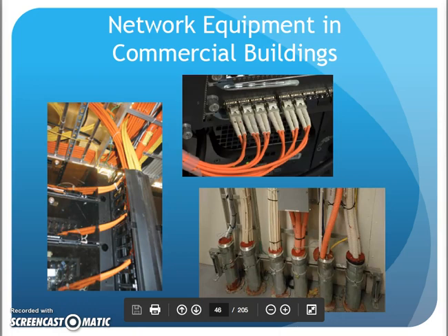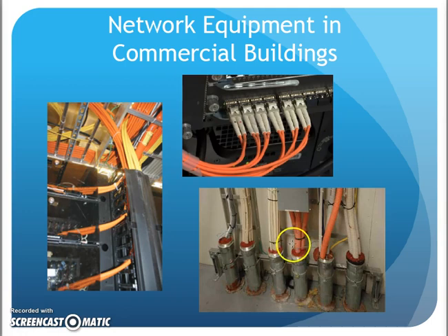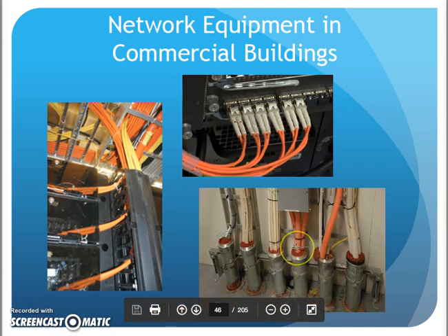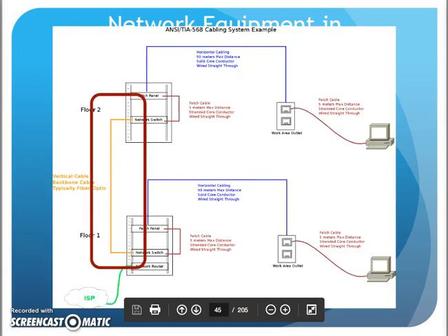And here is actually some examples of some backbone cabling, some fiber cabling going between closets. And literally in a multi-floor building, there is a hole drilled through the floor, a metal sleeve put through, the cables go through. Here's actually fiber innerduct. It's a plastic hose, almost reminds you of a swimming pool hose, that the fiber cables go down through. That hose is there for protection and a guide. And then after all this goes down through this conduit, this sleeve between the floors, you have fire retardant clay, for lack of a better description, that goes in here. It's called fire stop.